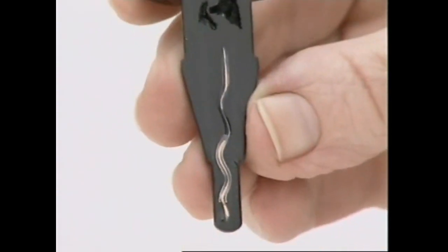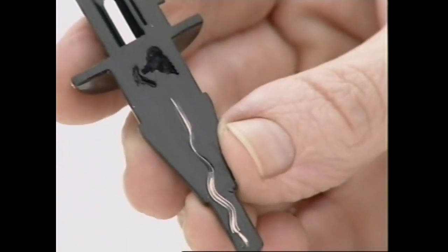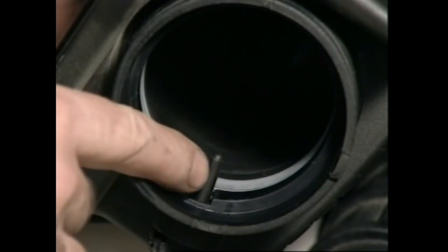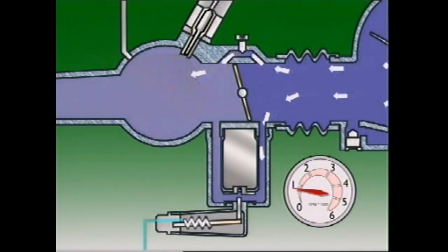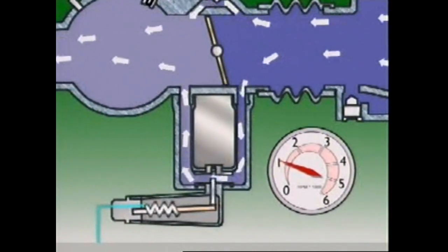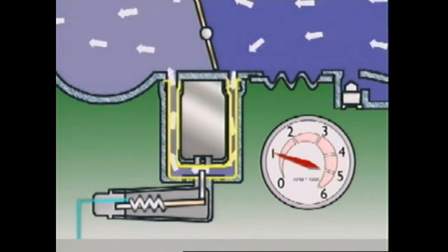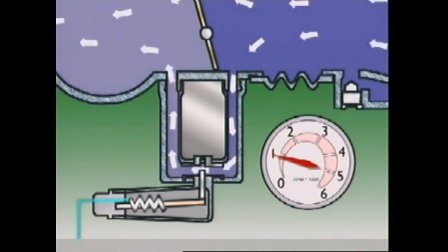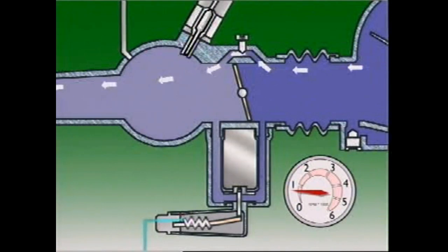Variations in air density, according to temperature, are measured by the air intake temperature sensor. It's installed in the main passageway, protruding into the airstream. During cold starting, the engine needs extra fuel and extra air also to provide a suitable mixture and increase idle speed. When the engine is cold, an auxiliary air valve lets air bypass the throttle plate. As the engine warms up, the valve gradually closes. This keeps idle speed fairly close to the basic setting of the idle speed adjusting screw, which is on the throttle body.